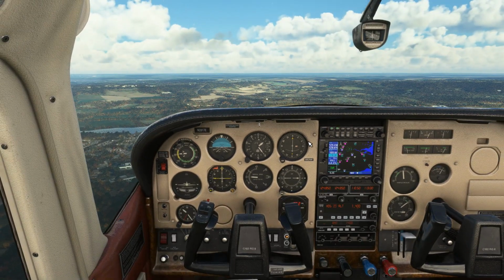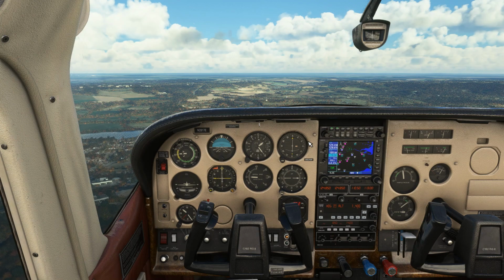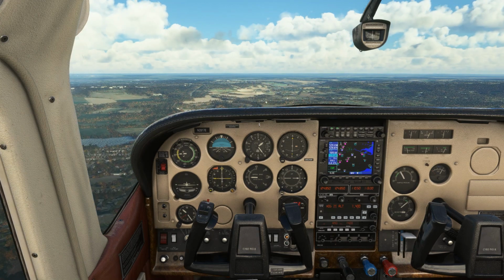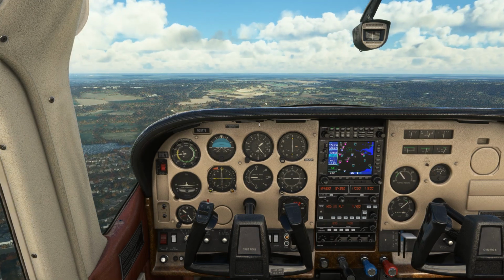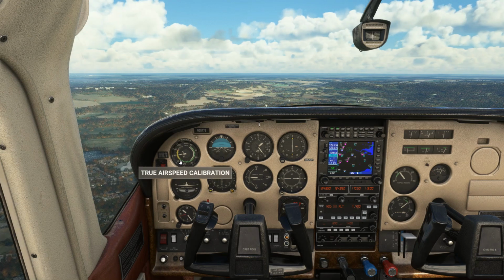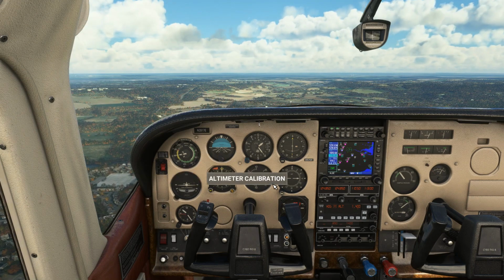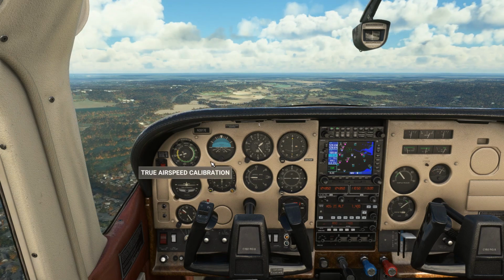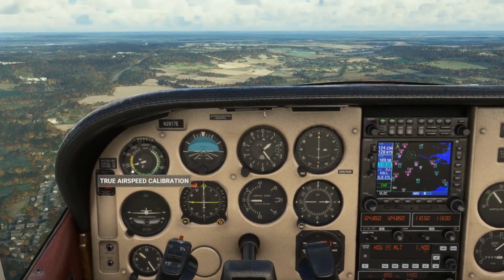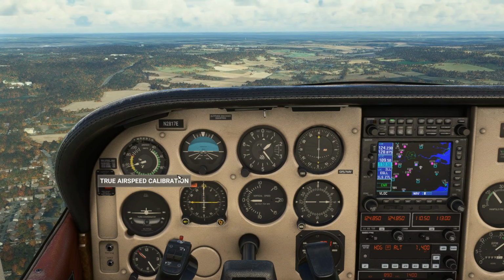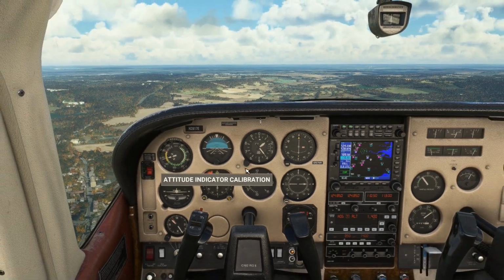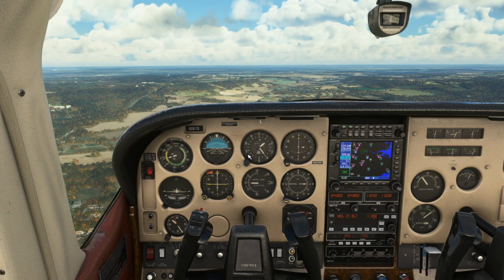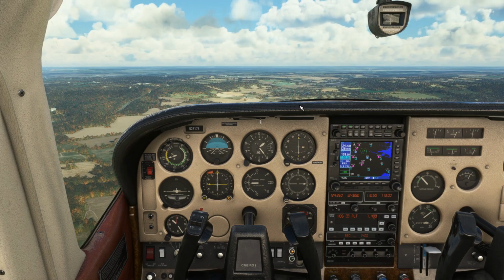Like I said, I'll do this in one cut. Now, I'm above 160 knots. I'm going to bring back my throttle. I've got it now to around 70%. There's no need to go that fast. As you can see, the airspeed is dropping. So if we zoom in on that, you can see that's dropping slightly back towards 150. Probably get it to around 140 knots. So bring it back to maybe 60%, and that will do.